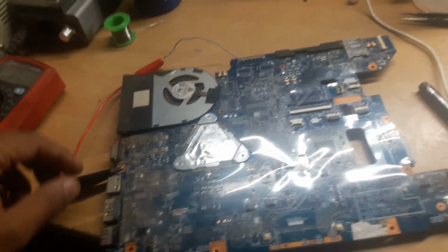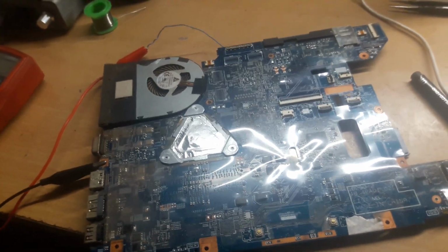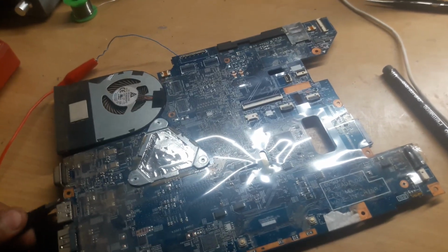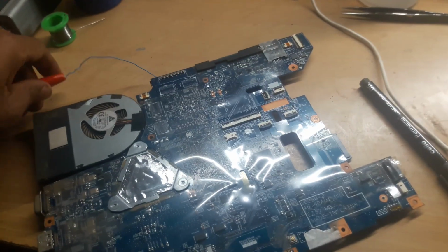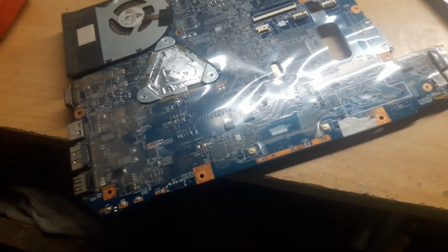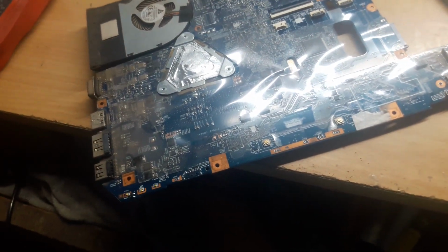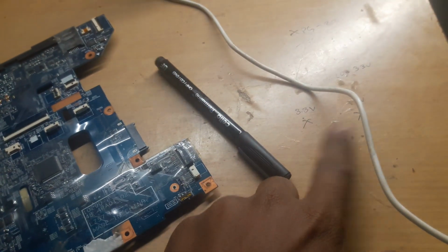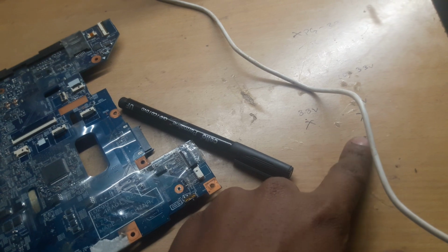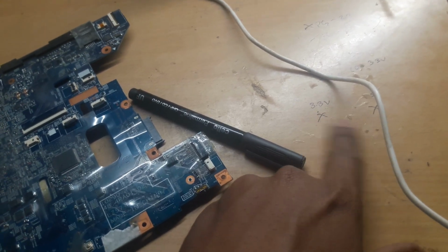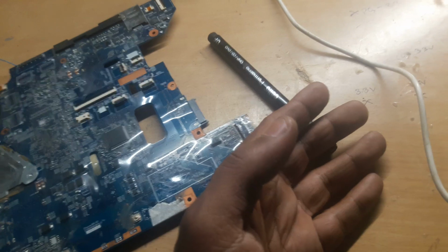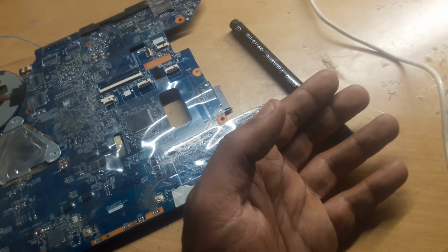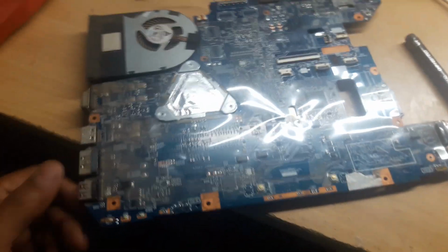So this was today's case study, in which we just replaced our DC to DC IC, which is the 5 volt and 3.3 always IC, because all the input requirements were okay, its LDO was also okay, but it was not giving our always voltage, even when the enable was available. So definitely we had doubt on that 5 volt and 3.3 volt IC. I replaced that, and after replacing we solved our problem.